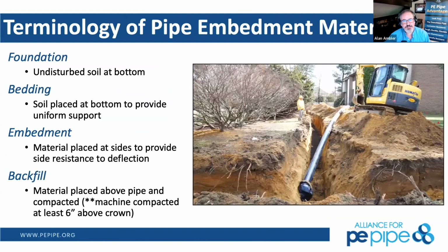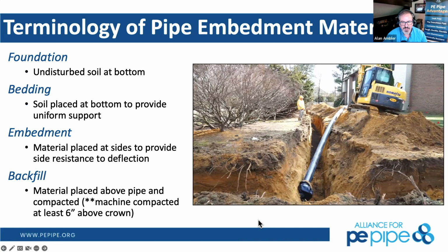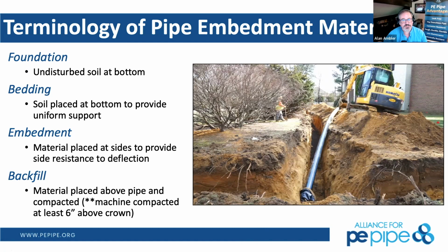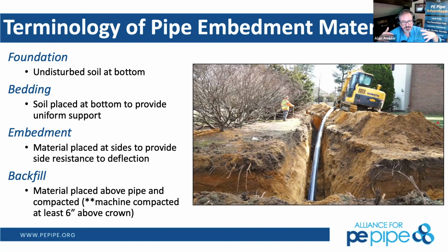Go back to the video, Pete. So I'm looking at this. Pete puts this one on social media, and they just love to try to eat him alive for it. Oh, the pipe doesn't have all the things that it needs to be able to be successful. That's not true. It's got a foundation, which is the undisturbed soil at the bottom. It's got bedding. The bedding itself is not compacted, so it's basically providing a safe spot, a void of rocks or other things to be on the bottom of that.